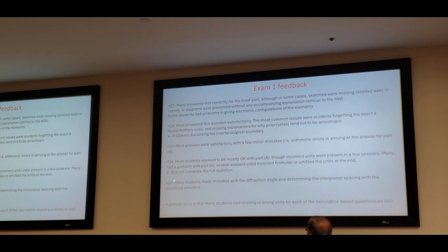Question number 5, many students made mistakes with the diffraction angle and determining the interplanar spacing with the equations provided. Again, I mentioned it many times in the class. Whatever you get from the XRD is 2 theta, but in the equation, you are supposed to use theta. Okay? So you need to be careful about those things. That's the advantage of coming to class.